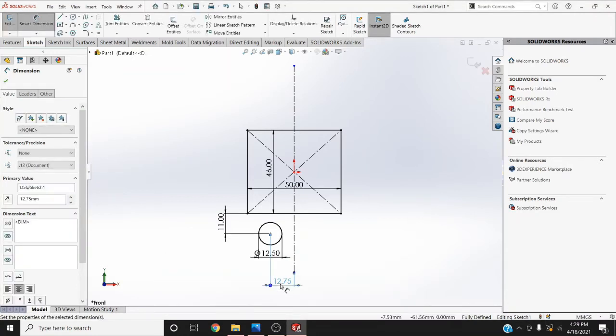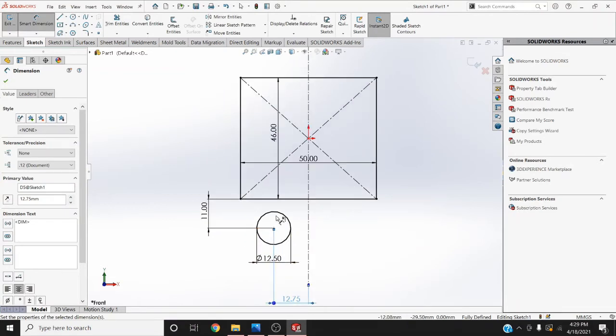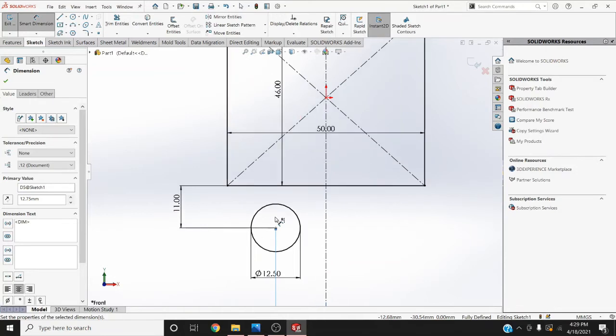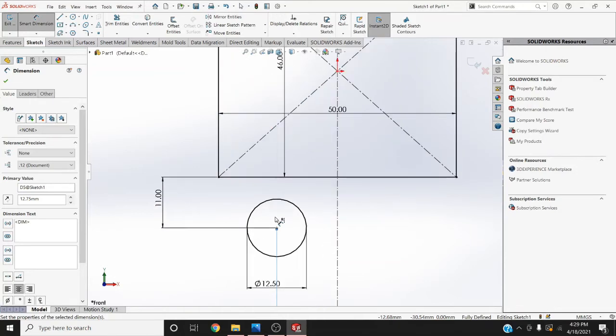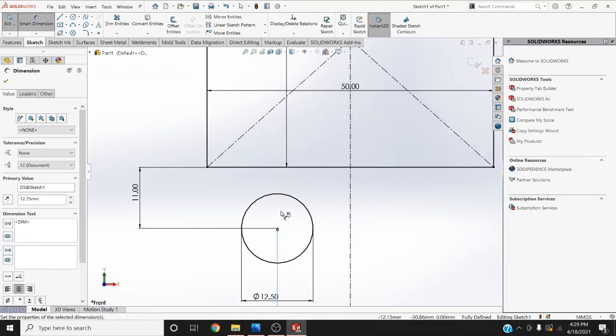Press enter in the modify box. Okay, there you go. Now I'm going to zoom in this place. The way you zoom in, make sure you have your mouse in the place where you want to zoom in. Okay, so I want to zoom in this place, right? So I would keep my mouse here and use the mouse scroll wheel to roll it and get it zoomed in.